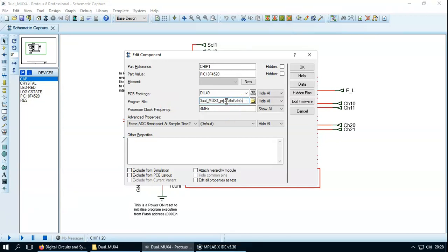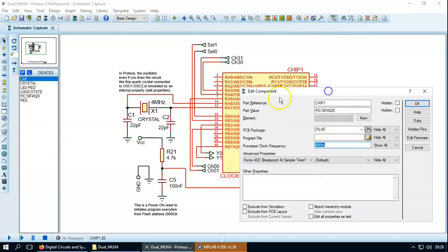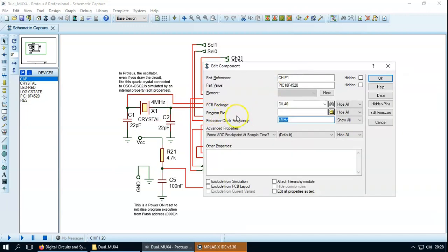You have no software now. And you can imagine that the processor speed, because this is simulated, is not the real clock, the real oscillator that you see in the schematic. Doesn't matter the value you've got here. What is important here is this parameter, processor clock frequency. So you can leave it like that for megahertz, but now the program is not really here.